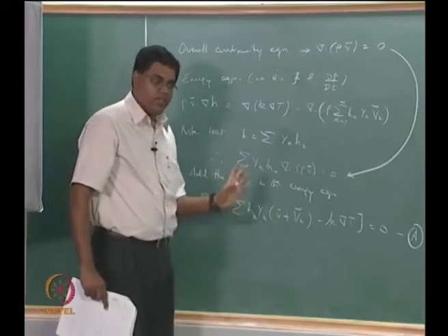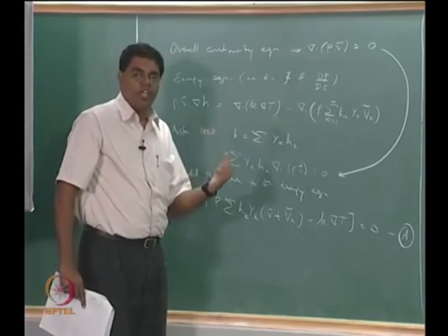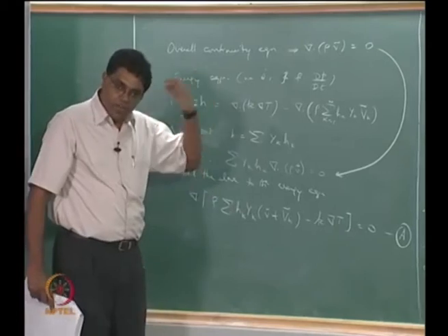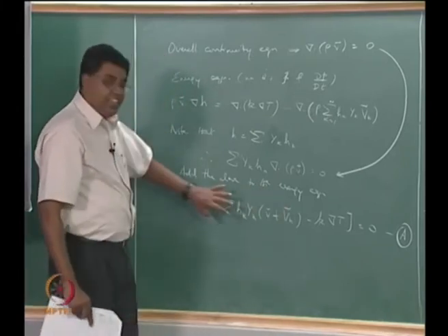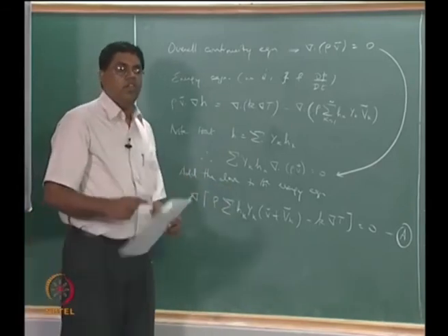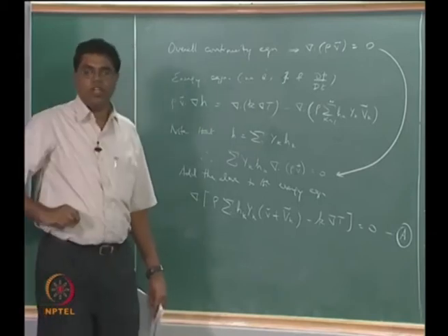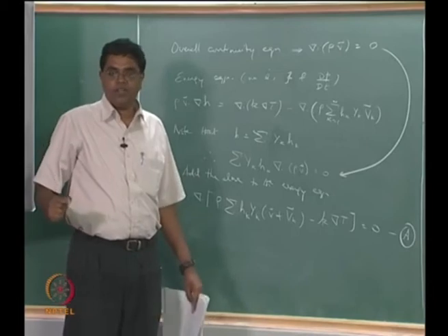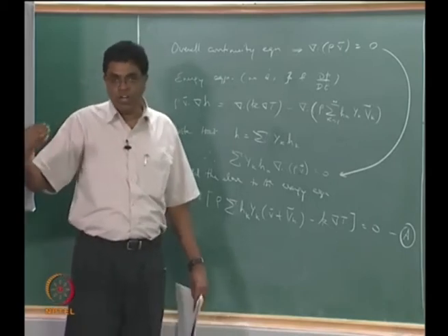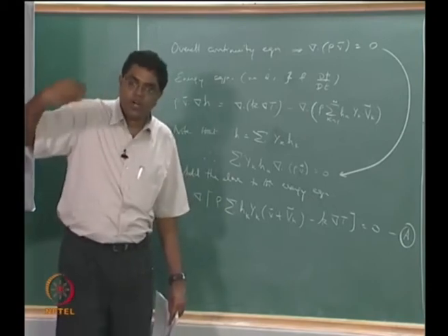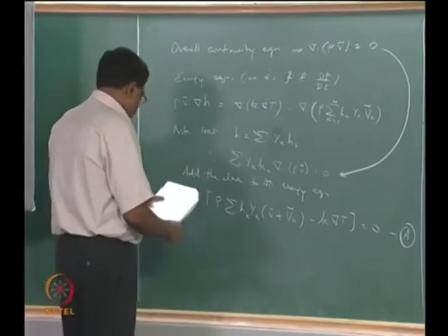So I will now be able to write something like a, for the term that has the delta H of k naught alone, I should now be able to write this as like a sigma Wk delta H of k naught. So Wk is coming from the right hand side of the species conservation, whose left hand side is this. I plug the right hand side of that here, for only that term which has the delta H of k naught. That will simply mean the chemical heat release rate term is nothing but the reaction rate term times the heat release from that reaction. That's correct, because a reaction is going to give rise to a certain heat release per unit mass of the fuel or any of the reactants. If you now multiply that by the rate of change of that species mass per unit time, then you should get the heat release rate. So we will try to look for that manipulation soon.